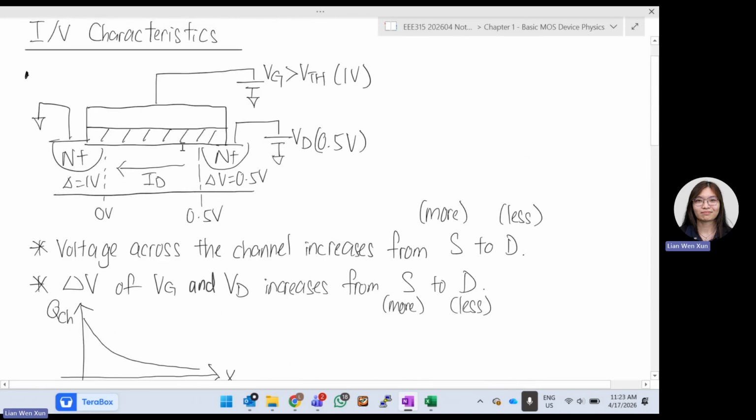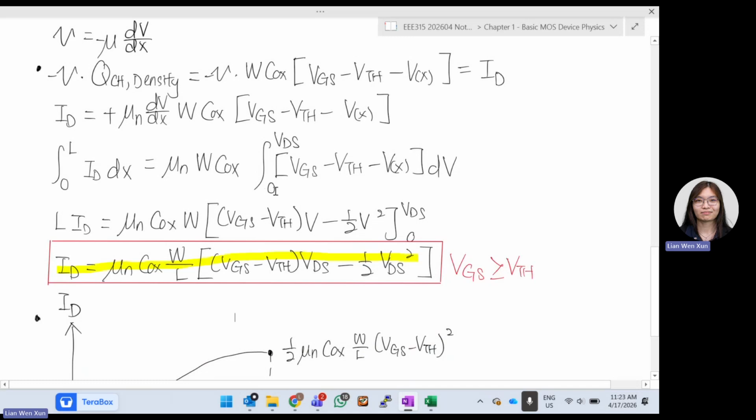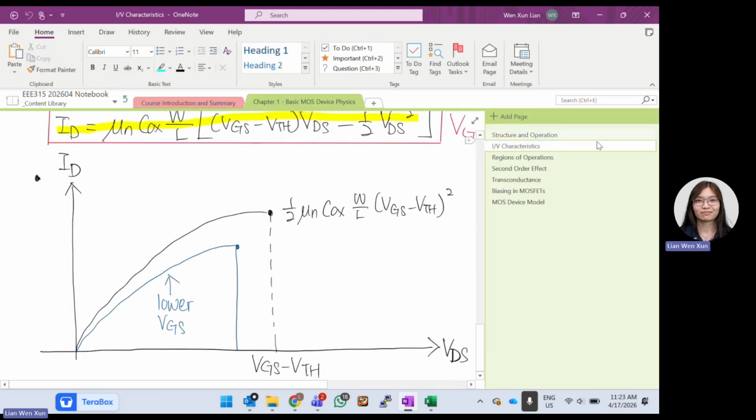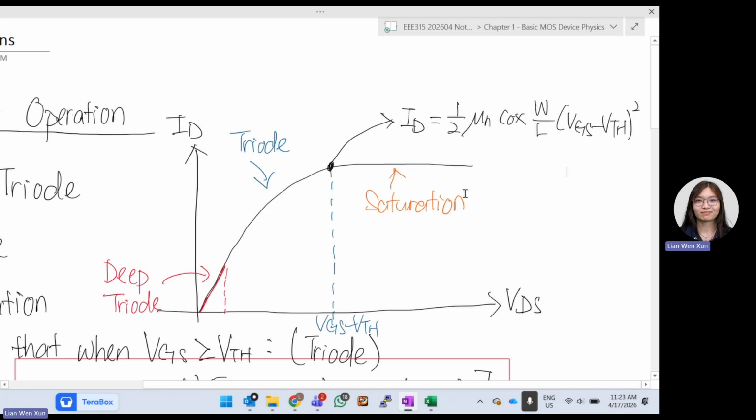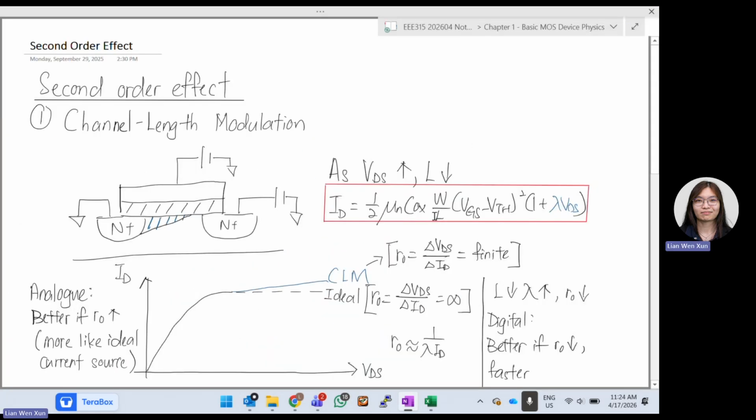So just now we settled the part where we don't use drain voltage anymore, where we integrate from 0 to VGS minus VTH, but we haven't settled the length part. Here, this length is supposed to change. So this 0 to L is not really the L anymore. It is the L depending on your drain voltage. So actually it is changing. That's why we have to include it.